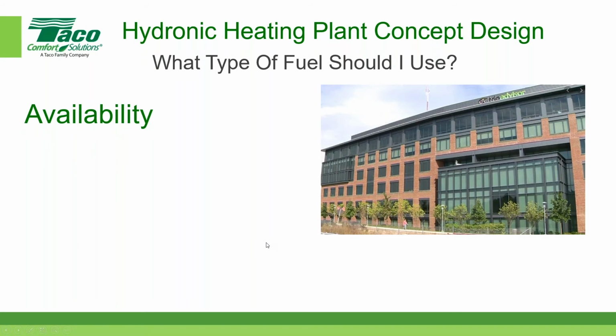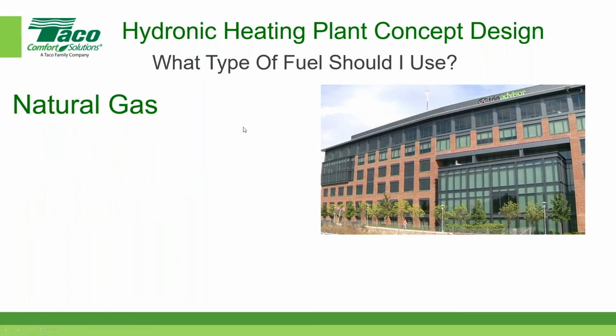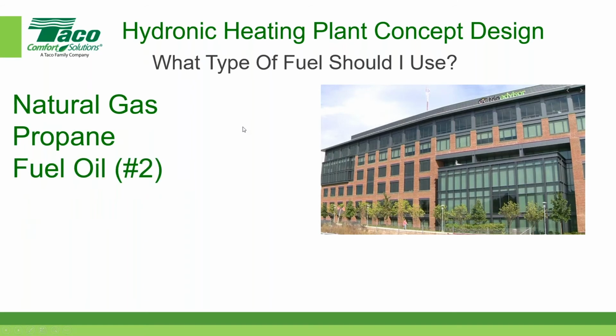So when we talk about what type of fuel should I use, the first thing we want to think about is availability. And I'm going to cover each one of these in a little bit of detail here. We're also interested in the cost, the heating value of the fuel, and whether or not the fuel requires any storage. So let's talk about availability. The fuels that we are interested in today are natural gas, propane, or fuel oil number 2.